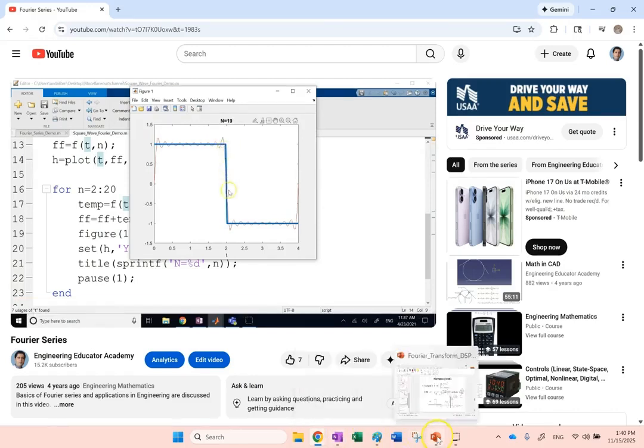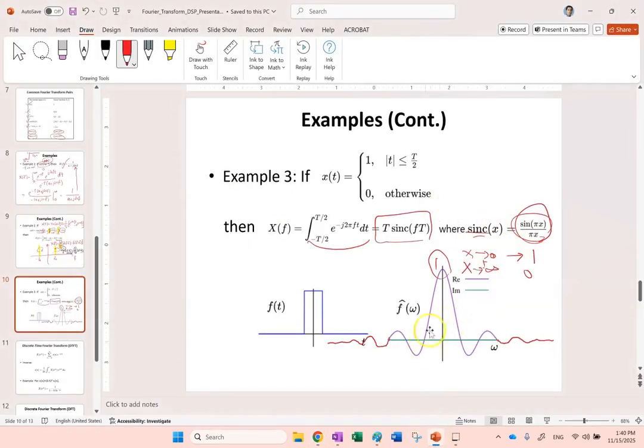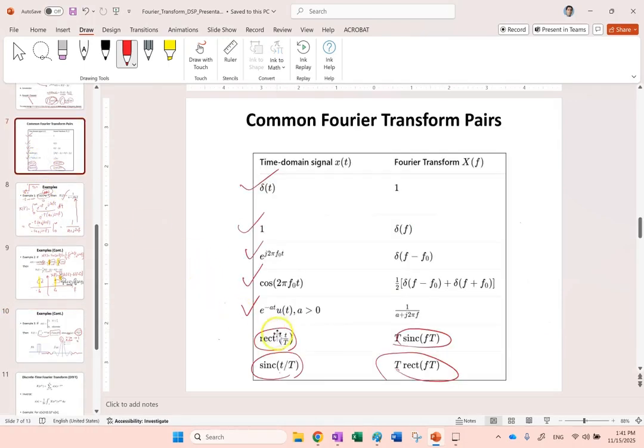So when you look at this plot, this absolutely makes sense. To make this, you need a big fixed number, probably in this case 1/2, and then you need a bunch of sines and cosines. First, some magnitude for the low frequencies, but a much smaller magnitude from the high frequencies to regenerate this. So this is your sinc function, and that is for rectangular.